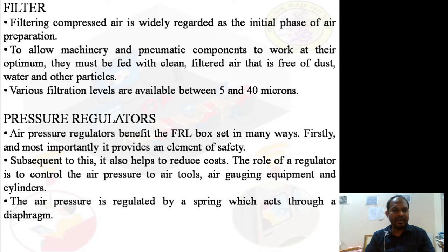So various filtration levels are available between 5 and 40 microns. Generally a dust particle will be approximately 60 microns in size. Even chalk powder will have a size of approximately 70 to 80 microns. So this has to be filtered.